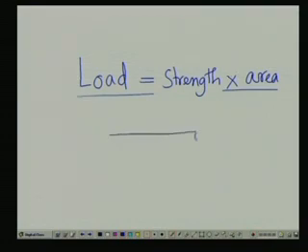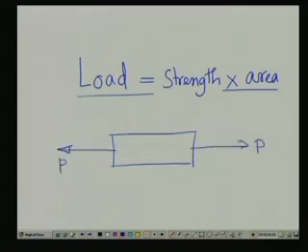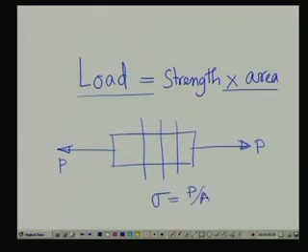See, if you have a machine member acted upon by a load P, you know at any section what the stress is. At any section 1, 2, 3, the stress sigma will be equal to P by A. What is A?